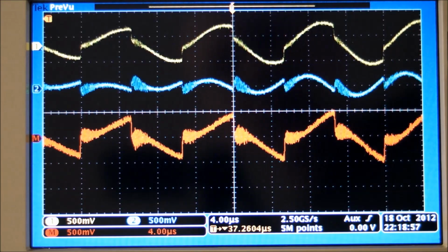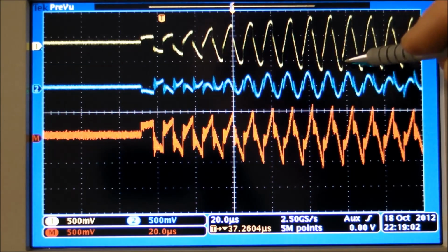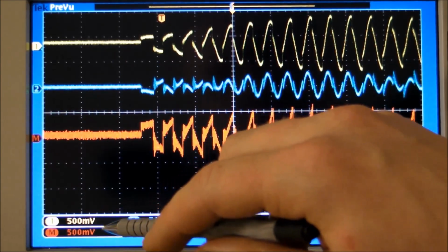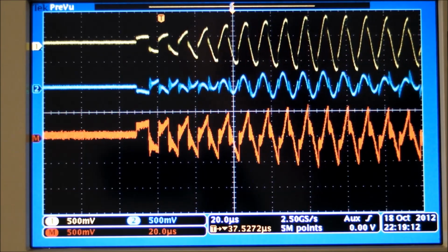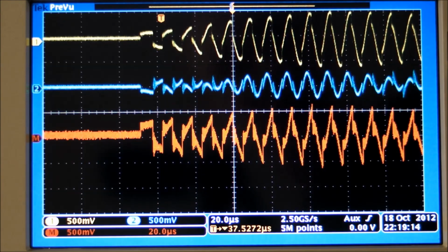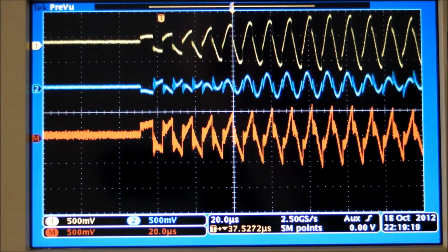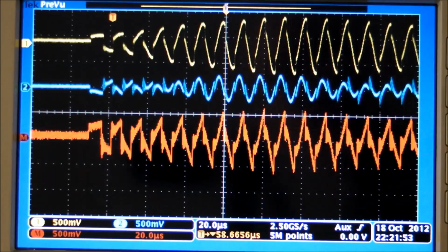But anyway, as far as magnitudes are concerned, you can see channel 1 is, we're looking at 5, this translates to 500 volts per division, so we're looking at about 1,000 volts peak to peak, or just 500 volts peak. Channel 2 is about half that, and the math function, the difference between them, is a little more than 1,000 volts peak to peak.